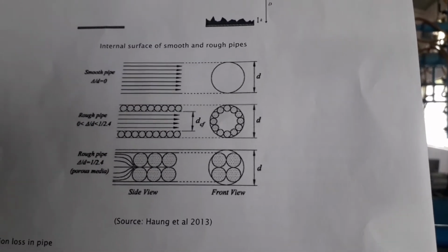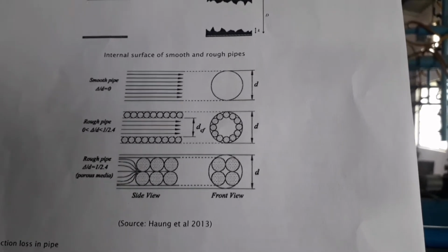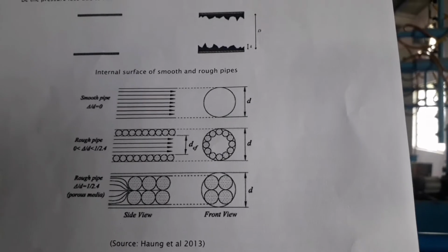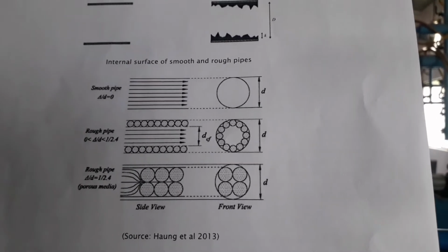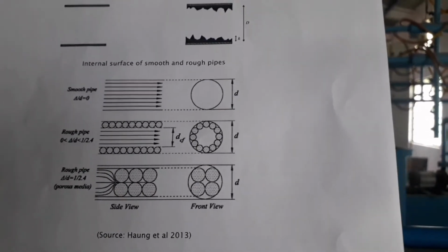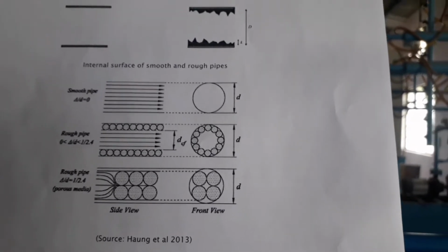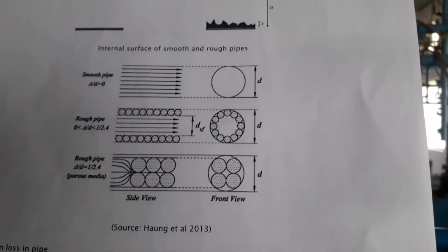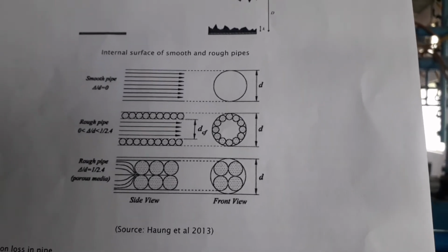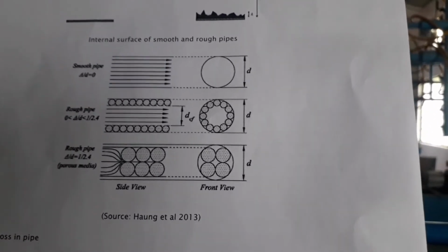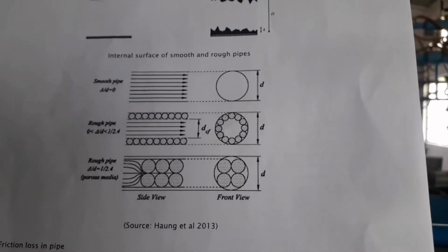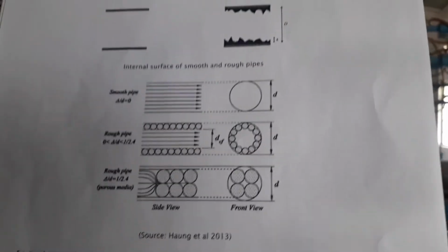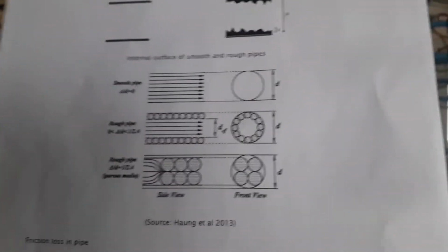Laminar flow occurs when the fluid flows in parallel layers without mixing between adjacent layers. In this type of flow, there are neither eddies nor cross currents, with fast flow over the center part of the pipe and no movement near the pipe surface. The roughness of the pipe surface influences neither the fluid flow nor the friction loss. For laminar flow, the Reynolds number Re is always less than 2100.